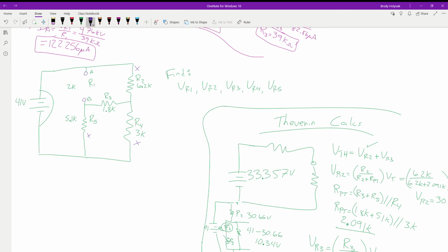So then that takes care of all the other connections. And the reason I stopped is because R5 is connected to point B, and point B we wanted to do later after we get everything else connected up. That way we're only moving from one point to the other point instead of jumping back and forth.